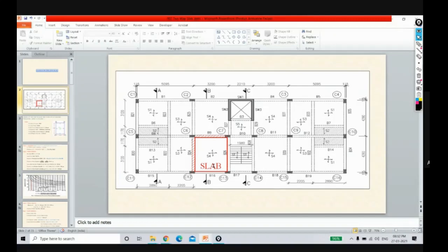First we have to check whether the reinforcement and depth provided in that slab are sufficient or not. Because if defects, deflection or cracks are there, definitely it's maybe due to the design, or maybe due to the poor material used in that particular slab.